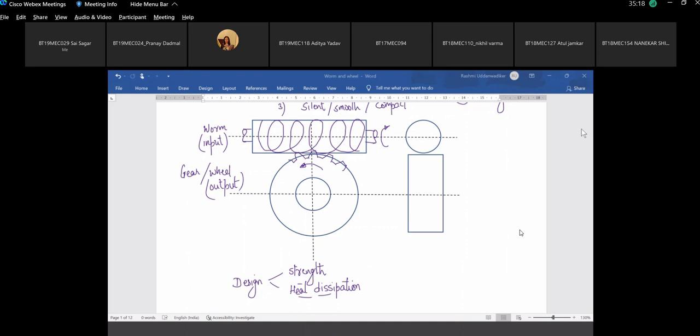Different geometry. Okay, not only geometry, because of rotary and translatory motion. Yeah, so to be precise, more than rotary and translatory, this screw on this worm and this tooth, they are more like sliding over each other, which is not the case in spur gear or helical gear. They are not sliding over each other. Although they are coming in contact, after it leaves the path of contact, the contact is broken. But here, since the gear tooth is sliding along the surface of the wheel, there is a large amount of friction, and also another reason is there is huge relative velocity.